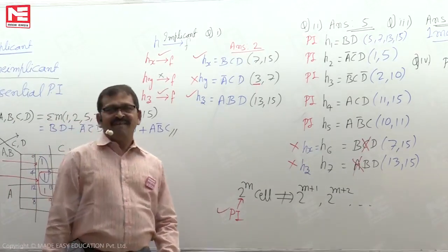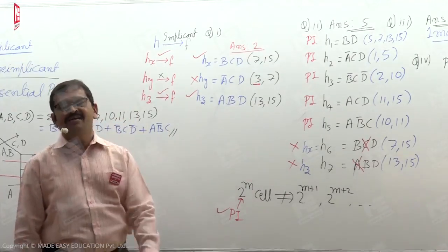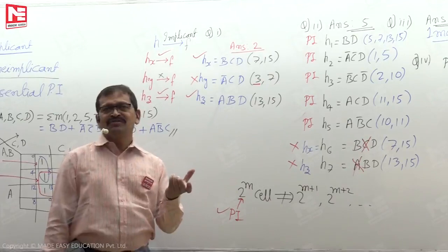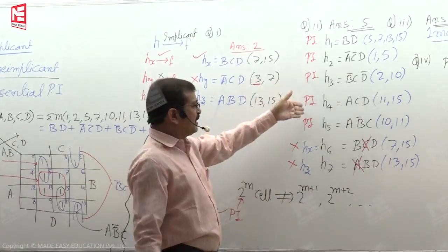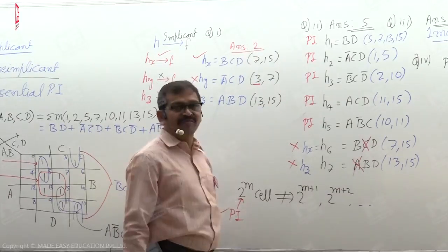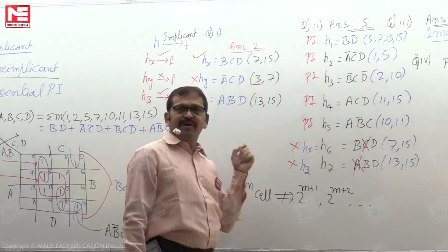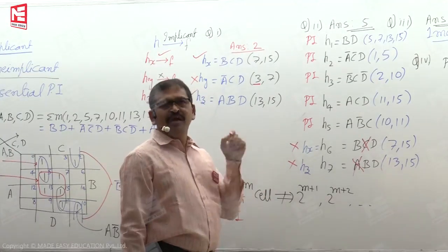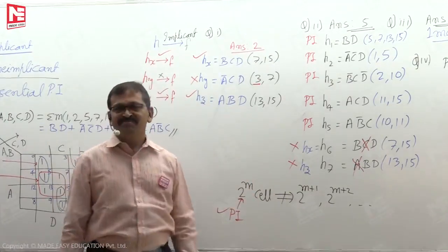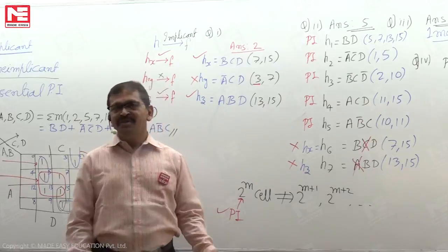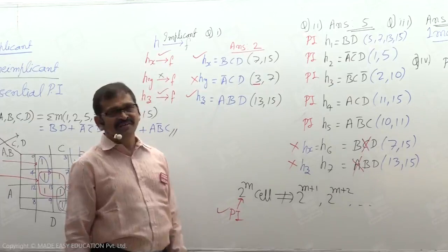In other words, for reading the minimal expressions, if we use the prime implicants, we are guaranteed the products have the minimum number of literals. So for reading the minimal expression, we can use this new terminology: we must use only prime implicants. A product is guaranteed to be a prime implicant if and only if you follow this condition. So it means the condition we mentioned earlier.